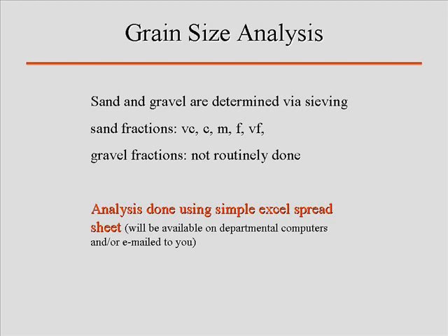Yeah, all right. For the pipette method, I've done grain size analysis on samples as little as 3 grams and got decent results. Now you should realize, the less sediment you have, the more potential error you're going to have. That's true with all methods. So there are issues with both methods. And ultimately, the real problems are going to be in how inconsistent you are with the procedures. It is possible to make mistakes.